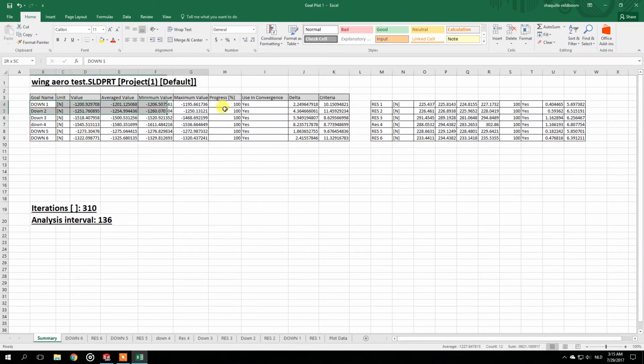So these two are the wings that have the curvature that is going towards the back of the car, so the usual car setup. And as you can see in the downforce numbers, they're creating the least amount of downforce. So there are 30 kilograms less than the straight wings, basically. And that is something that I really didn't expect, because I thought that these would create more downforce because of their increased surface area of the wing. And yeah, that is just something that didn't happen. So I was a little bit dumbfounded by these results until I saw the CFD, and it made a little bit more sense after that.